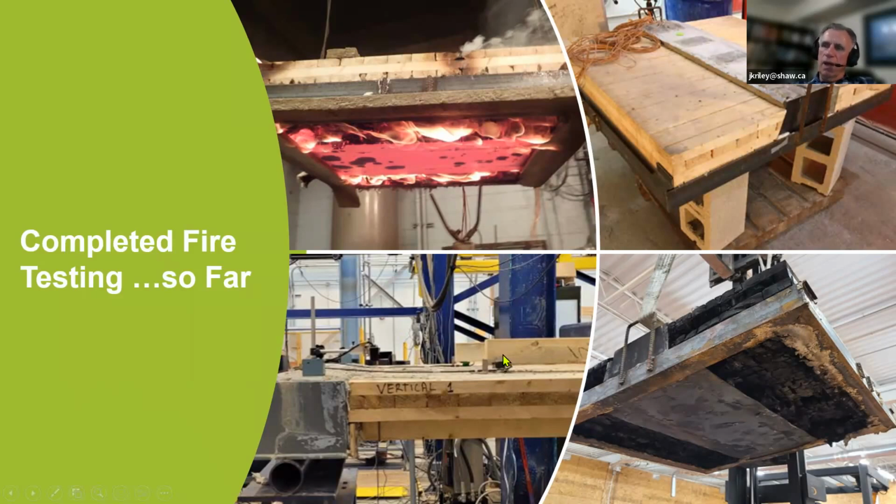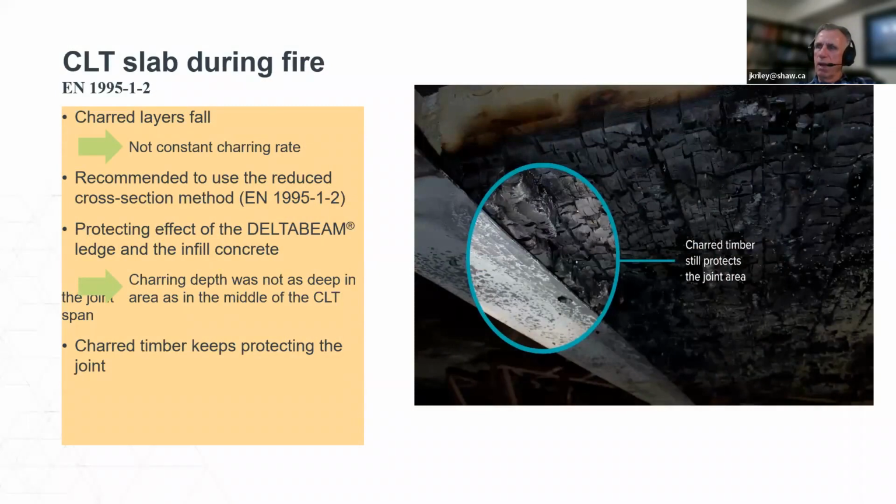We also tested loading on another assembly. And if you look carefully here, there's no bottom plate. So what we're doing is using 3 plies here. We're testing the loading to make sure that the loading works properly, which it did. And then we actually did the burn. So here the fire is burning at the rate of about 1.5 inches per hour, about normal. And you can see here the beam is glowing red hot. Over here, after the 1 hour, this is what the assembly looked like. Now, if you look carefully here, we're showing you here that the wood actually charred less around the beam than around the rest of it. So that's a significant fire design note that was observed in Europe, and we see it happening here in our fire testing also.